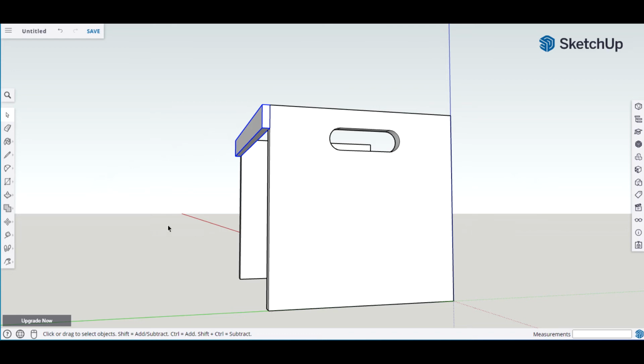So first step is highlighted, as I said. Hit the M key for move. Select this. Move it down a bit. Hit the Control key, because again I'm on a Windows PC. I believe it's the Command key on Mac. And now we notice we have two. Now don't do anything. We're going to drag this all the way down. Snap, see how it snaps in place. Click once.